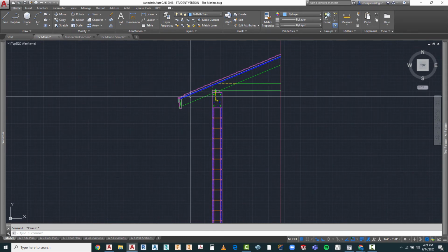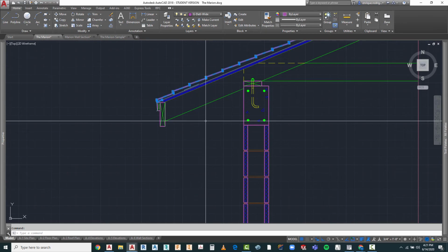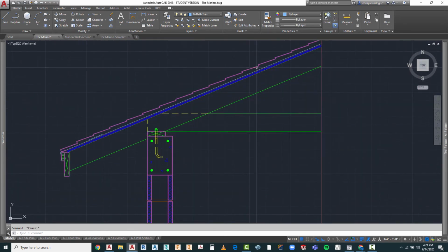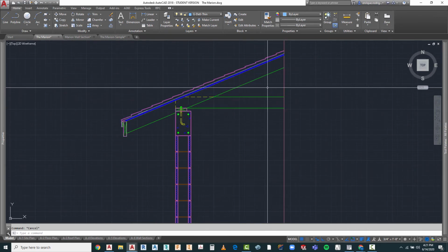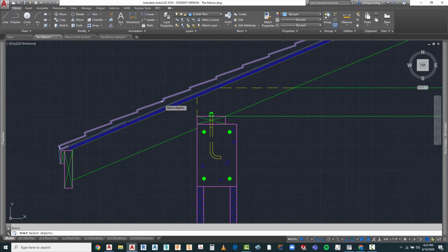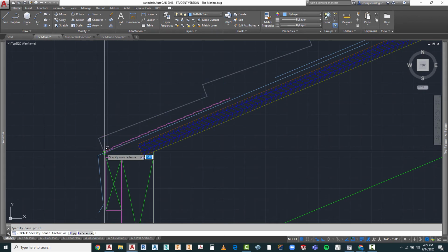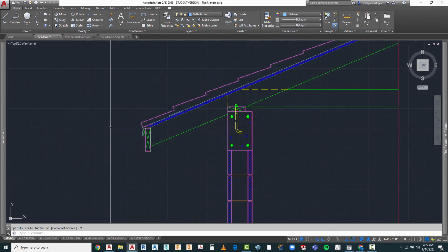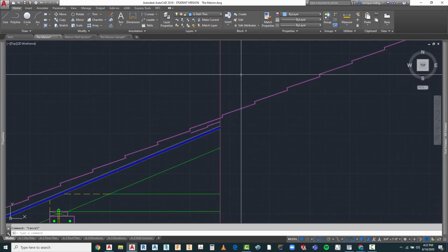And what we now have is our tile, and our roofing material on top. Now something's a little bit off. I'm not really happy with the scale of this tile. If this is 2 by 6, this is really tiny in terms of what that tile is. So I'm going to use a scale command, and I'm going to take it from this point and make it twice as big. That to me looks a little bit better in terms of what potentially the size of the tile might be.